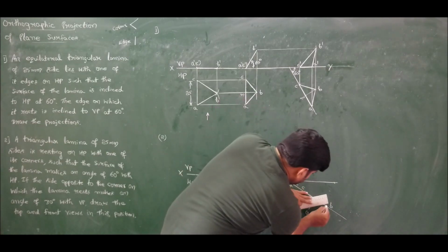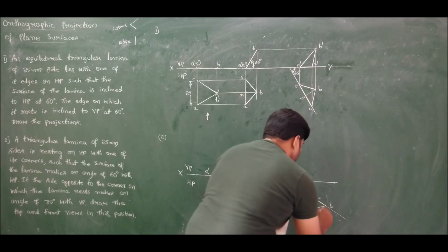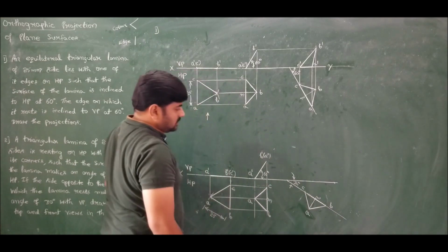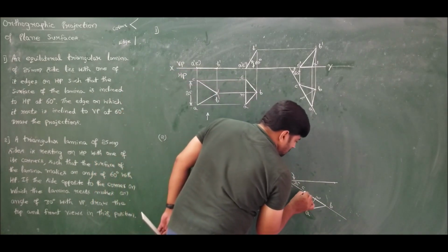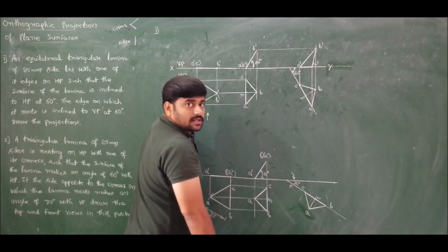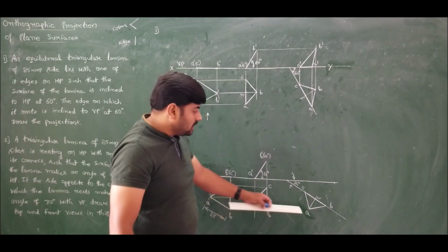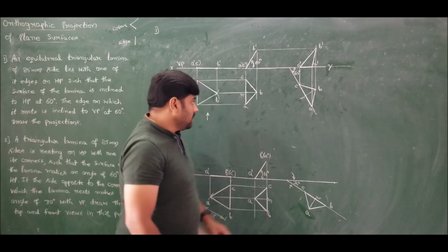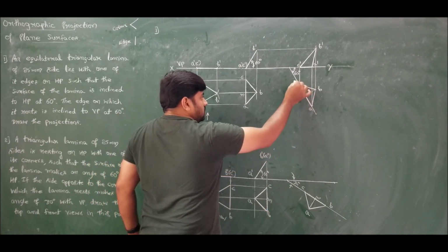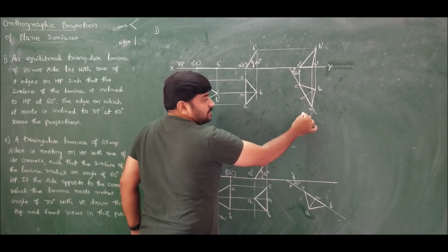So from there you connect. So if I connect, I will get ABC, such that this is inclined. Observer will be here. To the observer, the corner is nearer. This is the solution in which the corner is nearer to the observer. As I said in the front view, observer will be here. So to the observer, this edge AC is nearer in this position.